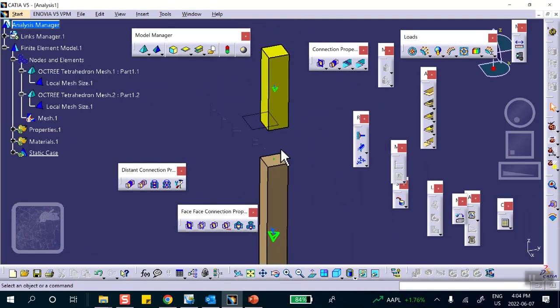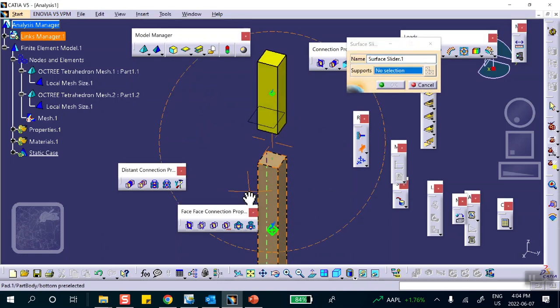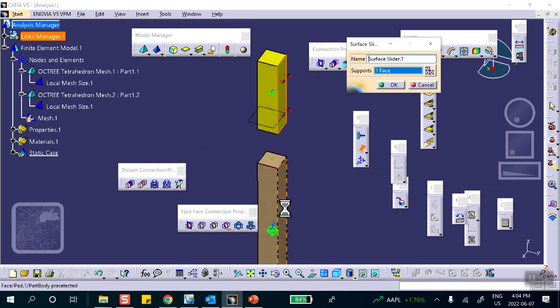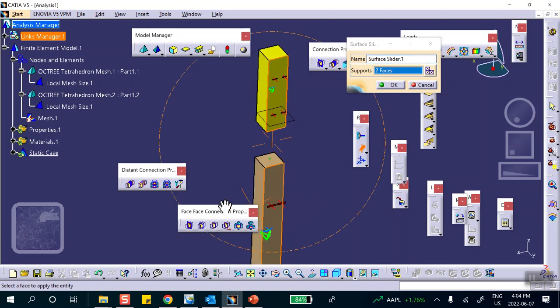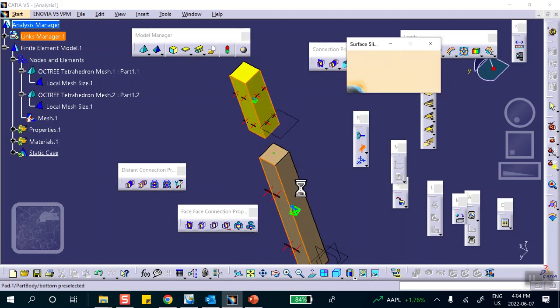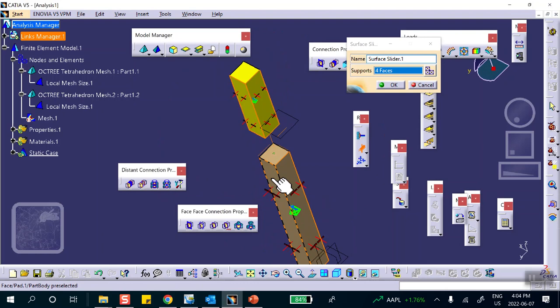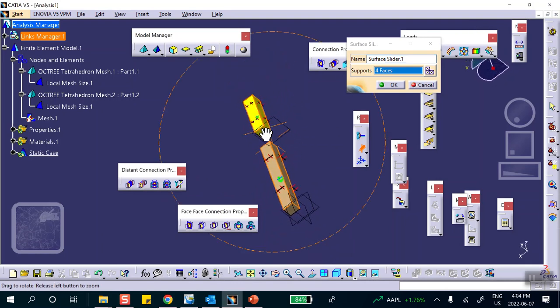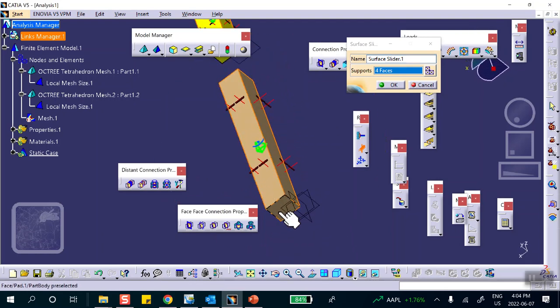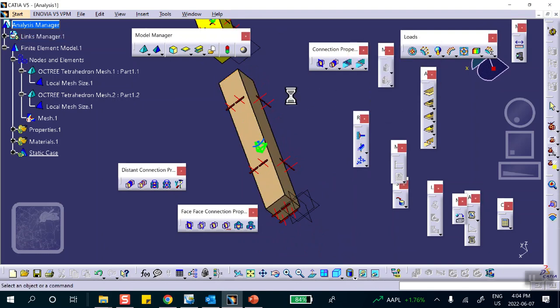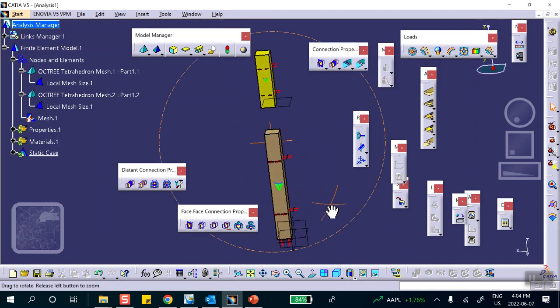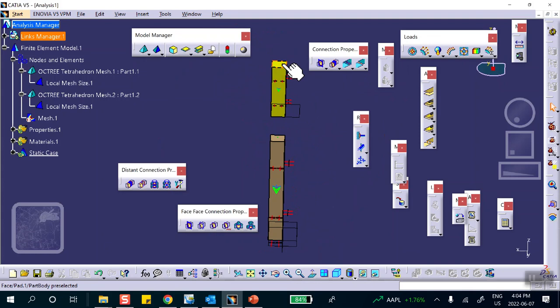All right. Now, we know that quite a few things are on surface slider because of symmetry, the cut that I made. This is on surface slider, that is on surface slider. Turn it around, so is this, and so is that, and so is the bottom of this bottom block. Okay, good. And then I want to push this top face down by some amount. Notice that the distance here was 1 inch. So first I make it 0 distance.